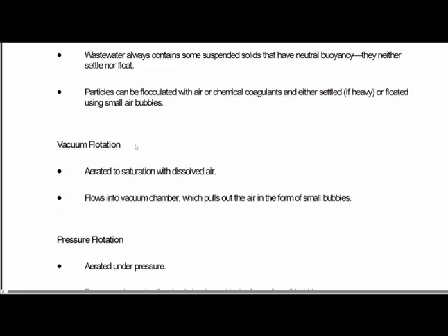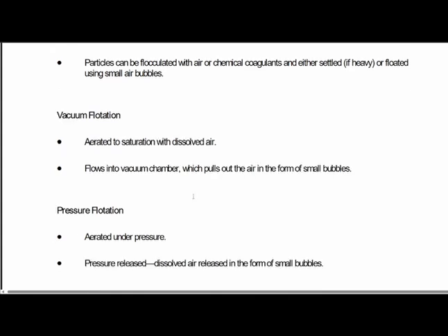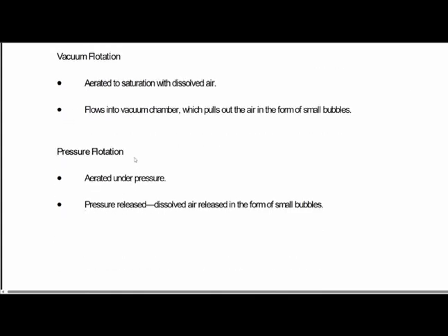Vacuum flotation. This isn't something I have experience with, but the wastewater is aerated to saturation with dissolved air, and flows into a vacuum chamber which pulls out the air in the form of small bubbles. Pressure flotation. Air is dissolved under pressure, and when the pressure is released, the air is released in the form of small bubbles.